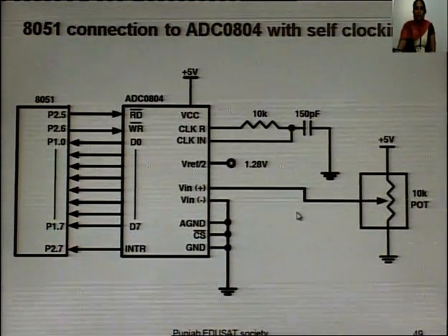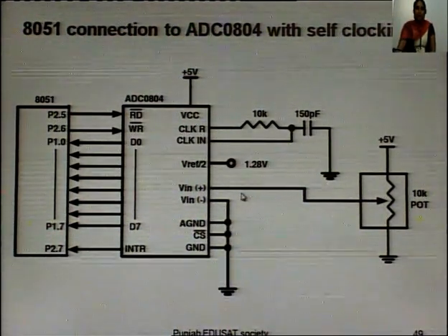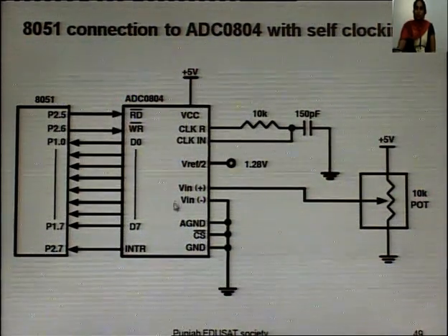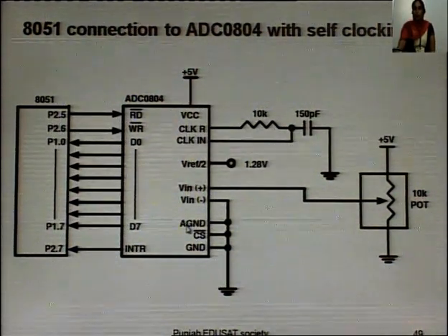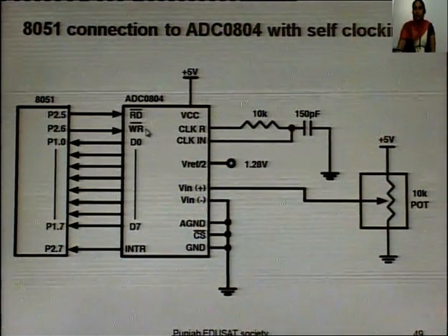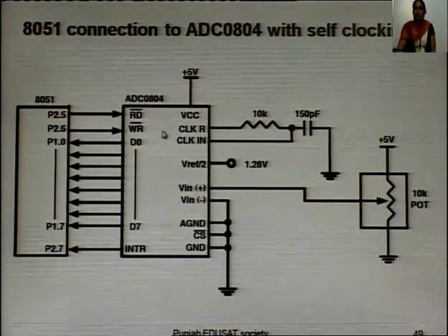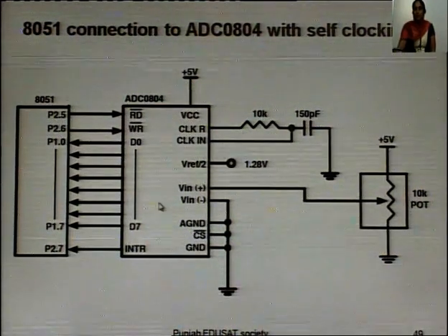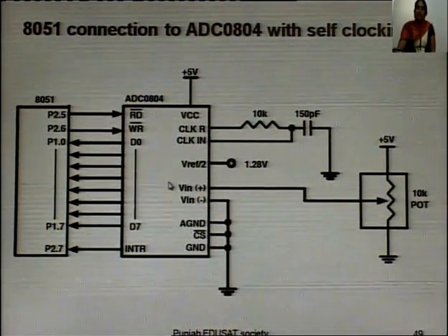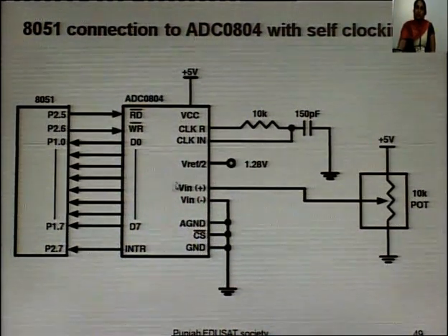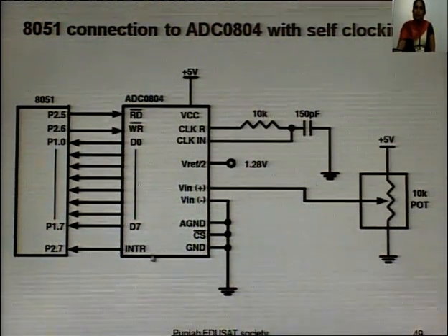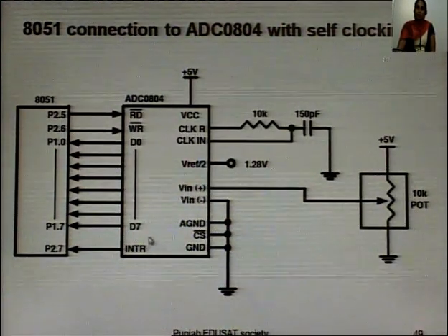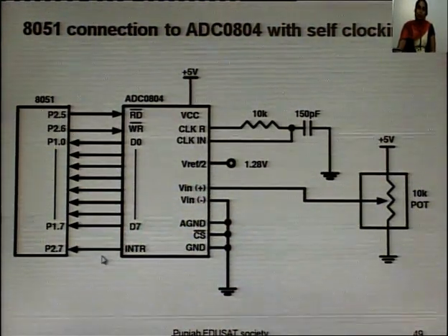Here analog data is given which is to be converted to the digital form. To convert analog data, first of all WR is made low, from high to low. It means your ADC starts conversion. When conversion is complete, your INTR pin, that is usually high, goes low.